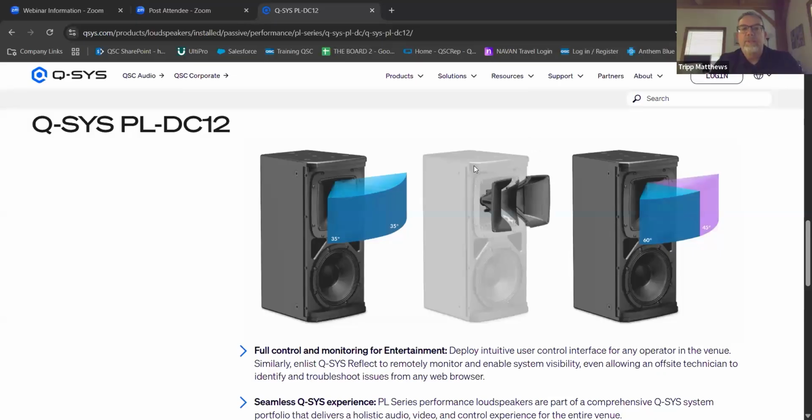We just put a generic block for random ceiling speakers, or we would do our ceiling speaker blocks, which didn't have a lot of changes to them. You put them in, you got your auto voicing put in, and you were off and running. And you really need to use the properties for this line of speakers, because the Q-SYS engine does most of your work for you. If you tune in the proper angles, the right segments, number of speakers, and all that, you will be in a really good place at the very beginning, no matter where you're at.